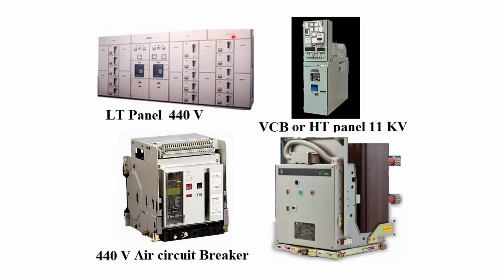This may contain a busbar on the top and a cable alley for taking in or outgoing cables. The bigger size of this may be MCB, MCCB, or it may have a switch like an air circuit breaker as well.